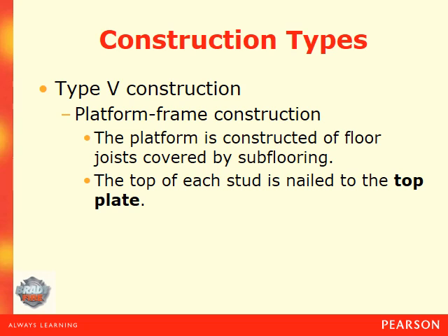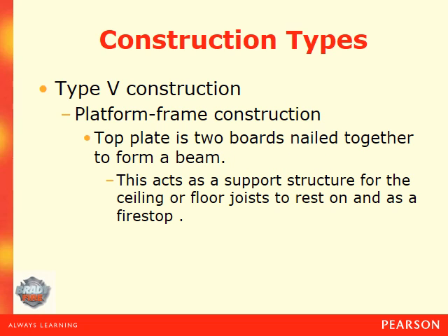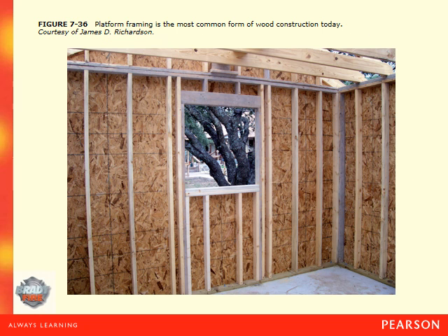The platform is constructed on floor joists covered by a subflooring, and the top of each stud is nailed to the top plate. The top plate is 2 boards nailed together to form a beam. This acts as a supporting structure for the ceiling or floor joist to rest on and as a fire stop. Okay, here's a good example of it as seen here and here.